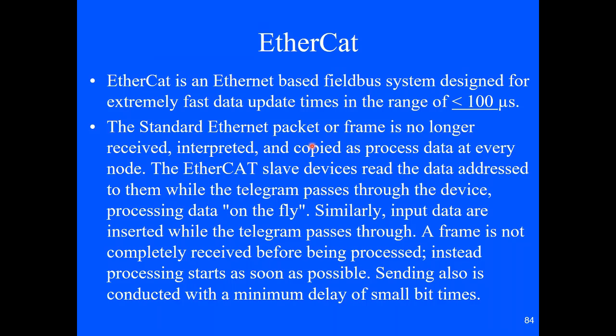EtherCAT's the last one I'm going to talk about. And what's cool about it is it actually starts decoding the packet. It's super, super fast. This is the protocol that I believe is in most automobiles. It actually starts decoding it before it's even received the whole packet. So it does it on the fly. So that's kind of neat.